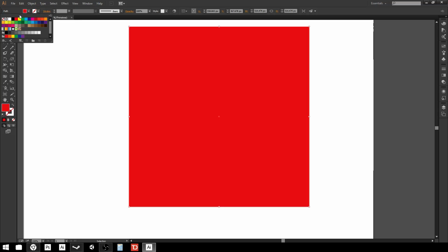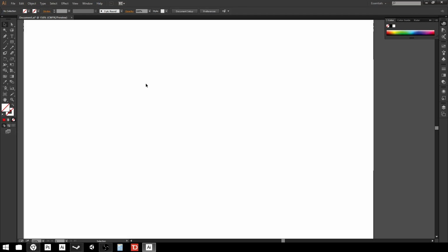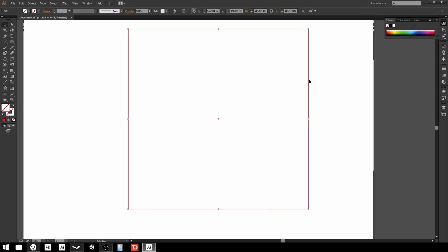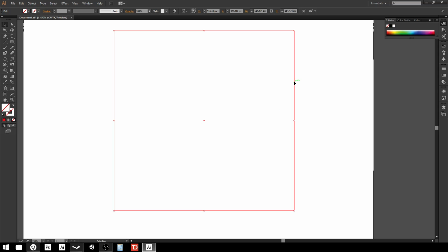You do that just by pulling down the drop and going to the option, the swatch option, that is a white square with a red line through it. I can also do it down here on the color picker by adding a stroke and then going to the none option. I can do that same thing by switching to the fill and going to the none option. Even if I remove both the fill and the stroke, it may be hard to see, but the shape is still here because everything I lay down creates a path. Now I'm getting into a lot of terminology here, but just be aware that a path is kind of the underlying, it is the core of everything you design in Illustrator.